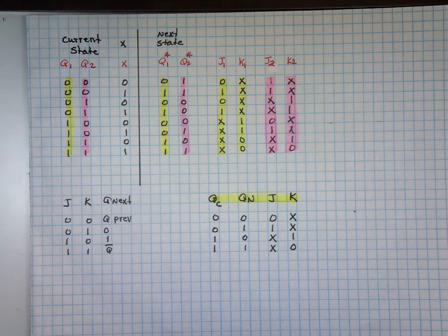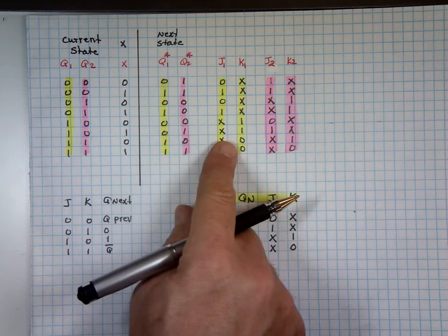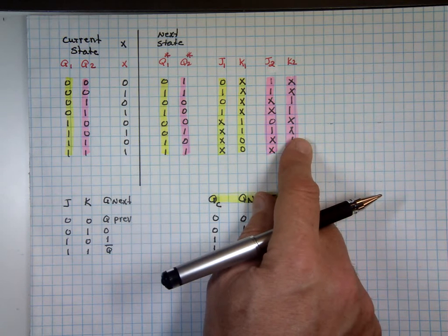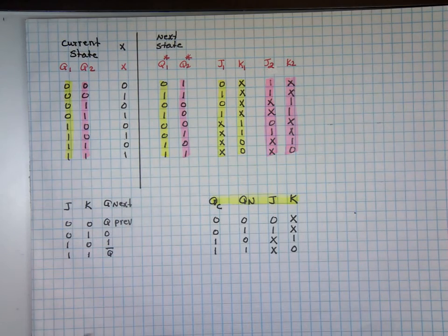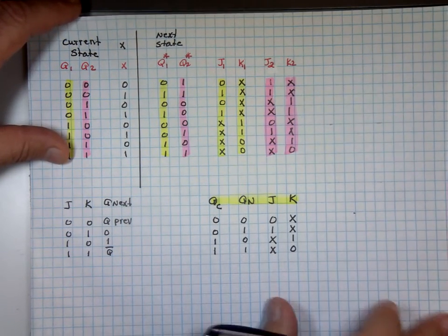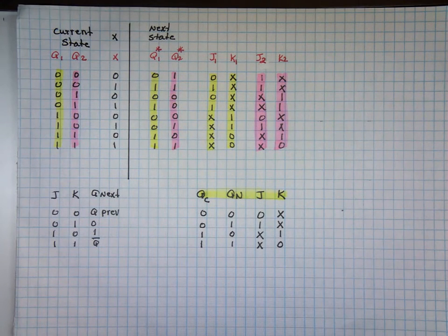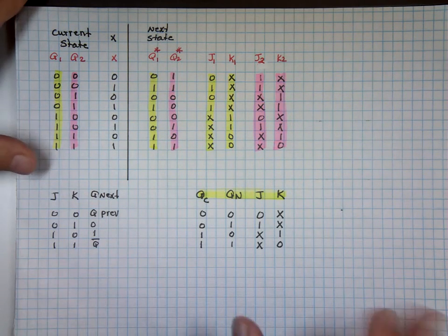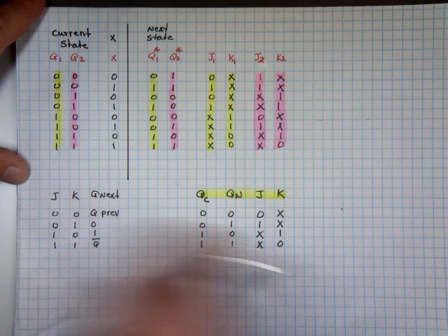Since I want to design the smallest circuit possible, I need to do a K-map for this, K-map for this, K-map for this, K-map for that. Everyone see that? A K-map for each one of them. That's part of the course, I think. It's the fun stuff. Love this stuff. You really have to be neat with this, you know. That's where these boxes come in handy. As much as people complain about the grid paper, it makes it easy on the eyes. I'd like to use the code so when people look at this and this to get that one, this and this to get that. I'm using this table actually to get these numbers. I got this from this one, working it backward.